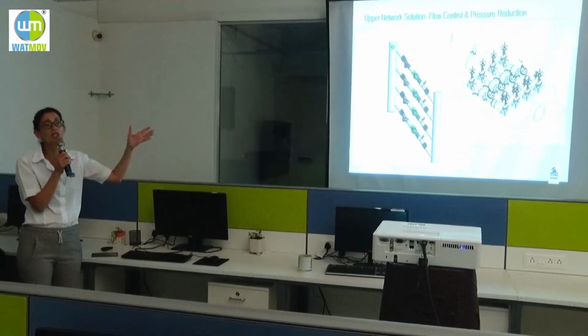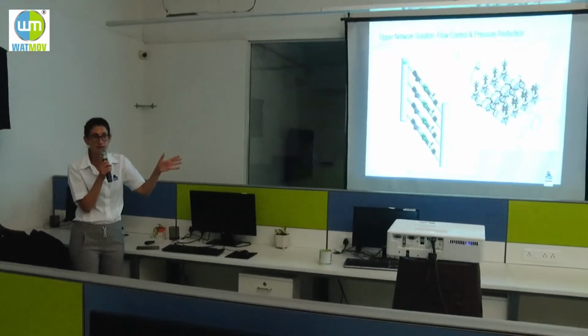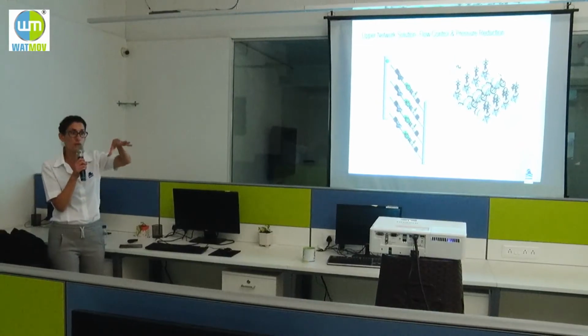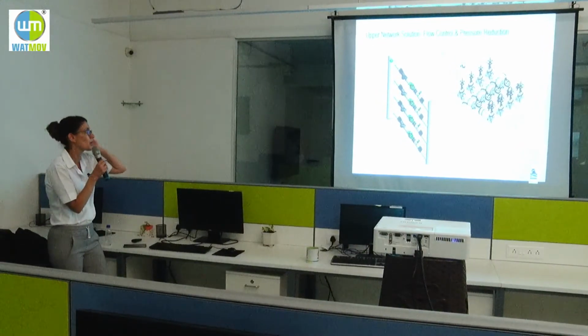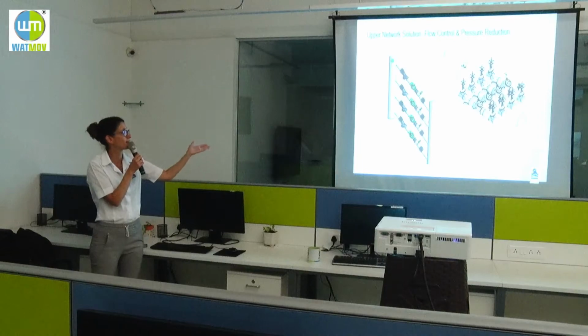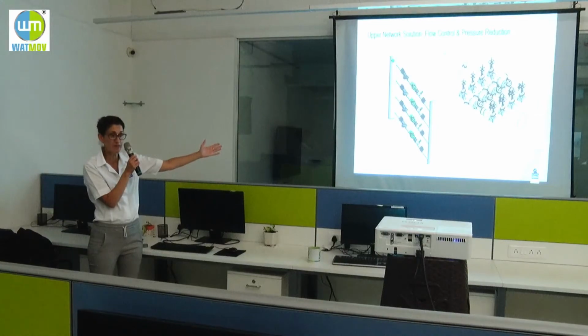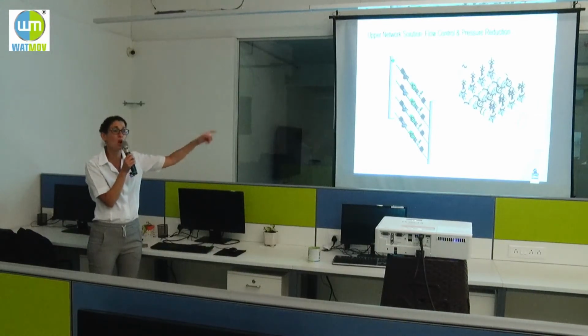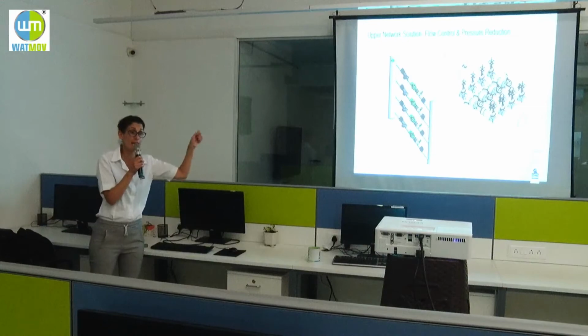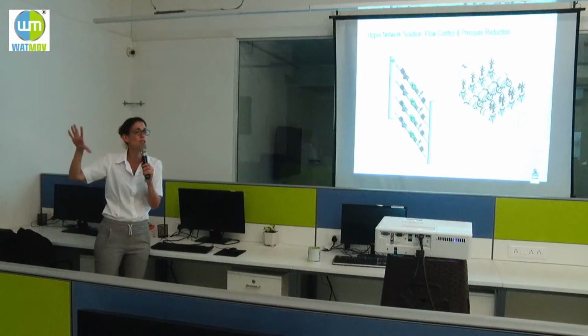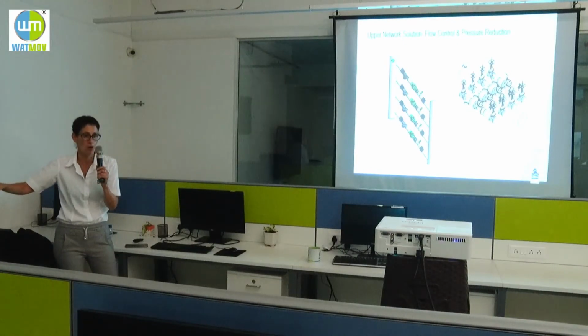Okay. So this is actually an alternative solution for BPT. Instead of constructing a BPT in the upper network, in those areas of critical zones, we suggested this mega station. You can see that we provided air valve, strainers, flow and pressure control valves. Here the flow control was additional safety on top of the flow control that we have in the OMS, for those colossal cases where something really went wrong.